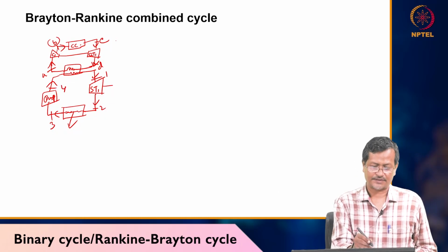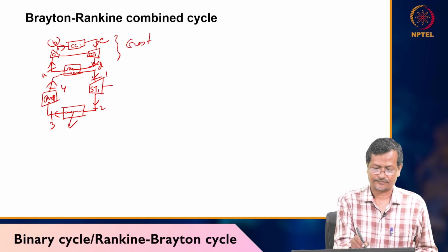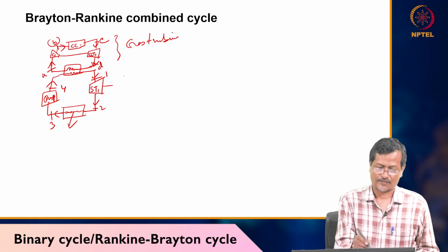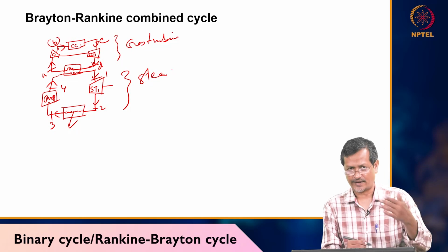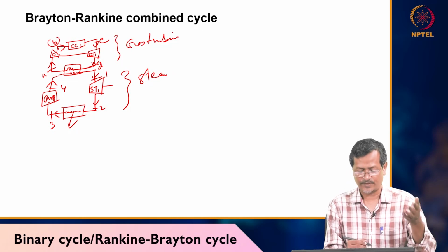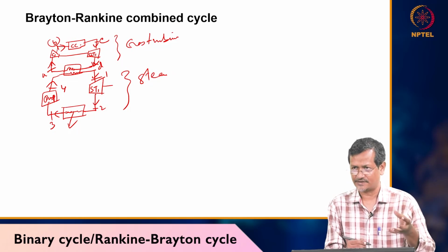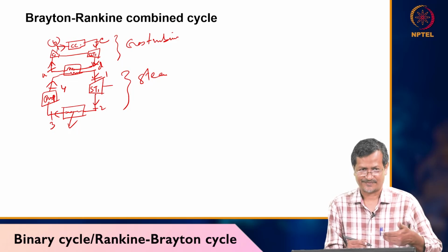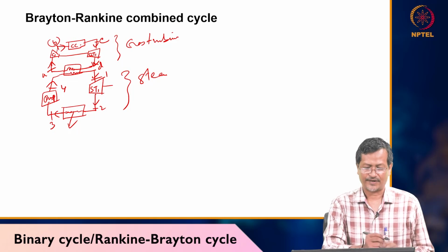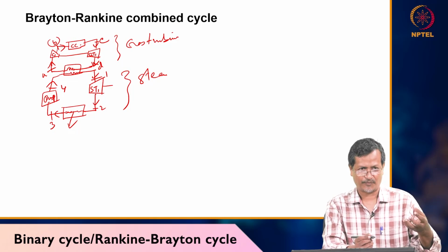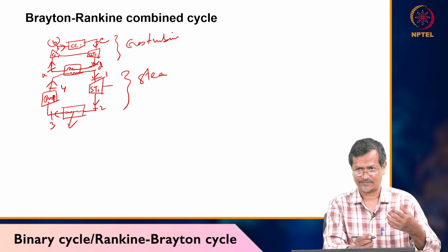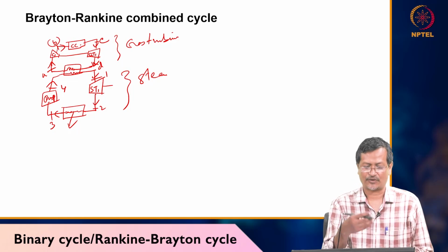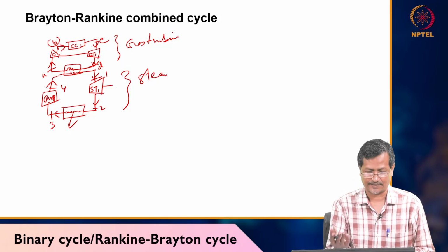Now you can see the top one is the gas turbine, this is the steam turbine. If you have any high heat source, or an IC engine with lots of waste heat, that can also run a steam turbine system. Anywhere you find waste heat, you can boil it and run a system which will give power. Normally it will be a Rankine type cycle.